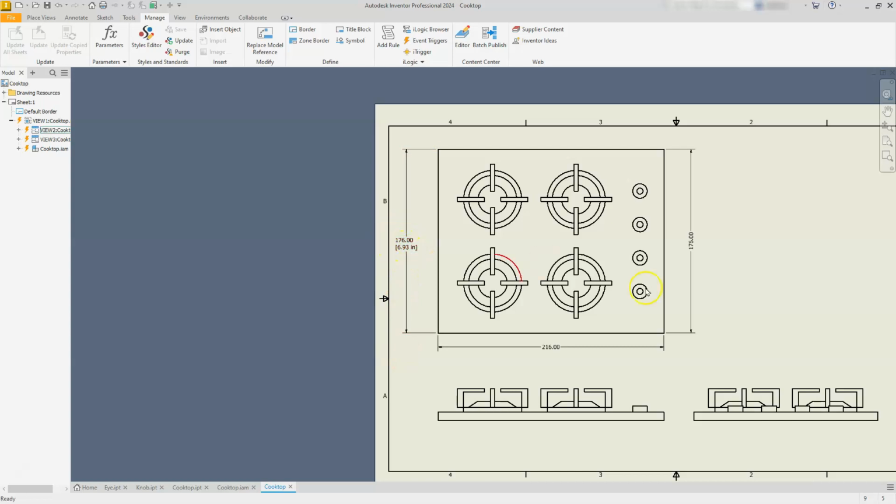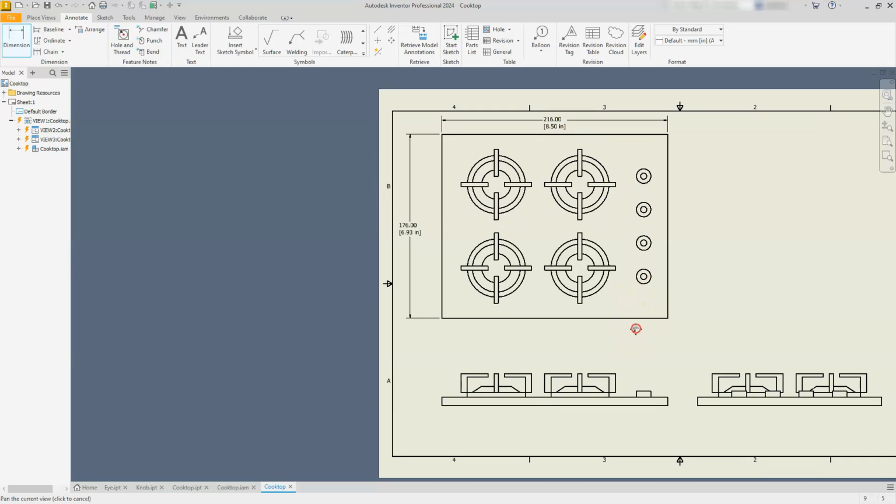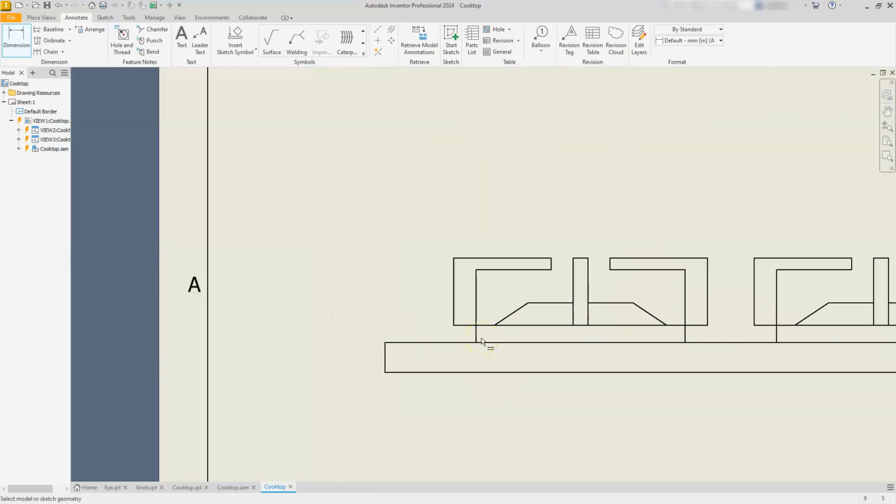All right. Let's go ahead and delete these dimensions and put the rest of these on there for us. I'm not going to show you all the dimensions, as you can follow along and do this on your own. But back underneath the annotation, I'm going to click on dimension. I'll click here. And you can see that I forgot to come in the drop down and select the dual dimensions, which is here. And then I'll go here and place that one, right?